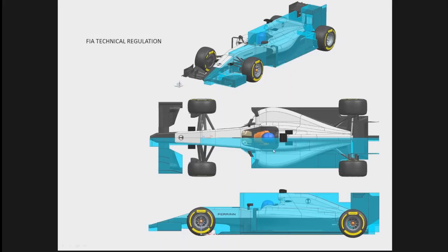We will see it later, but some of the vorticity coming off the front wing, for example, is coming from the discontinuity of the box that we can design the front wing into. Some of the top speed of the car is dictated by the size of the rear wing box. So you can see that it's really tight, and that defines what a Formula One car should be these days.